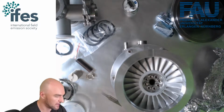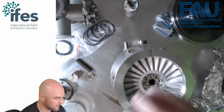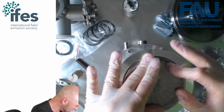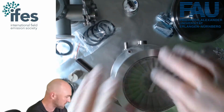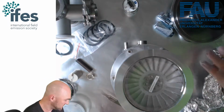So the area loss here is essentially a loss in pumping speed. But if it's mounted, for example, at the bottom, then there's not much you can do about it. You essentially have to use one of those meshes. Otherwise, if someone drops something in here, a sample or something, it will just blow the pump up.